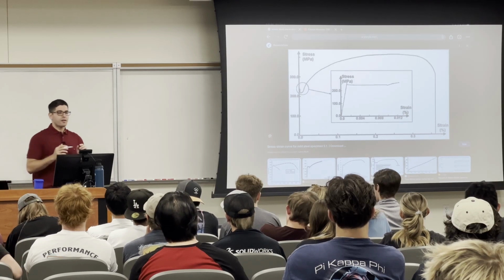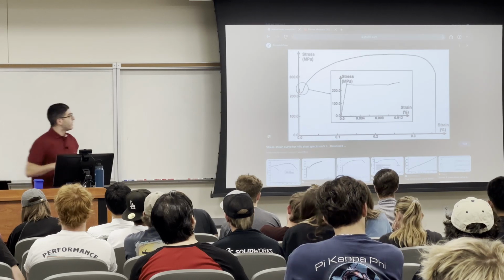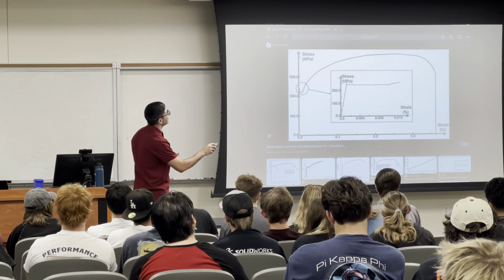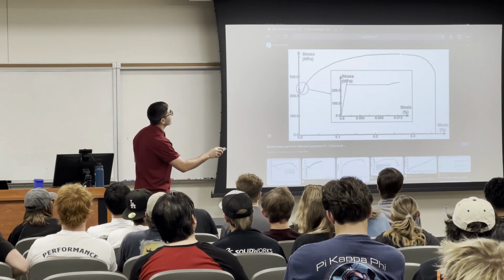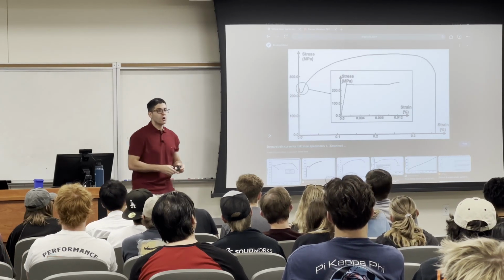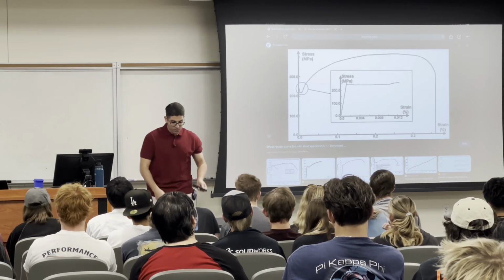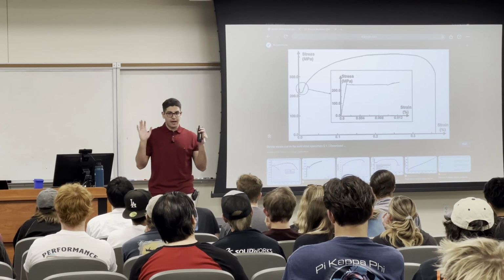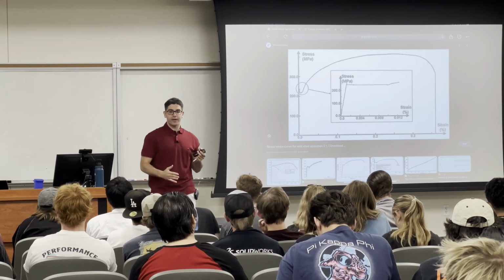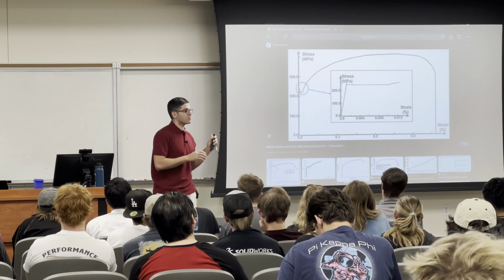Even at the top, at the same stress, even at a constant stress here, you'll have the material elongating. There is no increase in stress here, but there is an increase in elongation. So with a constant stress, that's when you know that a failure is going to happen. I'm standing on this slab, and I'm not increasing any loads, it's just my weight, and the slab keeps deforming until it breaks. So at a constant stress, you have a deformation happening without increasing any loads. That's when you know it's going to break.